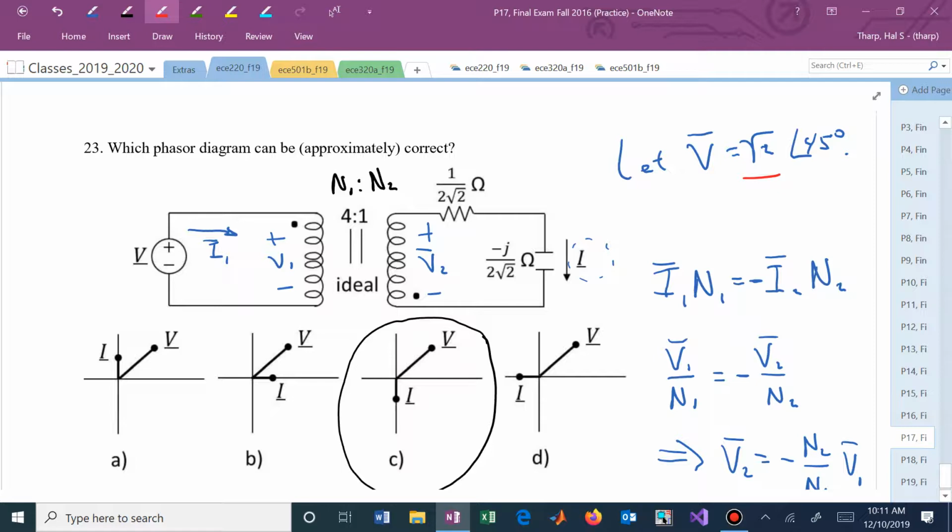So now the question is, if I now have a capacitor, you kind of have to play in 2 different rooms. Earlier this semester in Chapter 5, we were saying, oh, let's combine capacitors in series. And how do they combine? Like resistors in parallel. But now when we're dealing with Chapter 9, impedances, you just play with them like they are generic resistors.